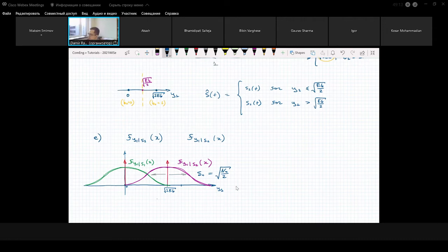It is not probability density, it's not power spectral density anymore, it is variance. And please, I would recommend you to check our previous material, where we showed that after processing, white noise becomes limited with variance N0 over 2. And of course, if variance equals N0 over 2, then the standard deviation will be the square root of N0 over 2. And this is what I have shown here.